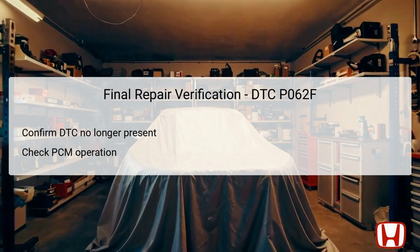After completing all the troubleshooting steps, it's now time for final repair verification concerning DTC P062F. This entails confirming that the DTC is no longer present in the PCM memory. Use the diagnostic scan tool to ensure that the MIL is off and that no pending or confirmed DTCs remain. It's not just about clearing the DTC. You must also ensure that the corresponding systems are now operating correctly.